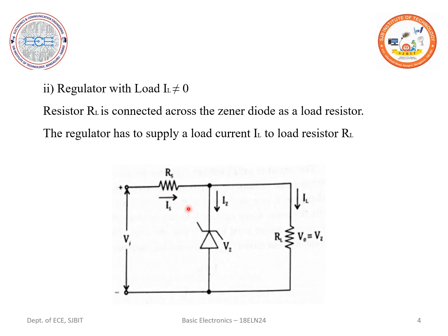Now always remember, whenever you connect your Zener diode to the input voltage, remember the polarities: it should be in a reverse bias condition. That is, the cathode of your Zener diode should be connected to positive and the anode should be connected to negative.